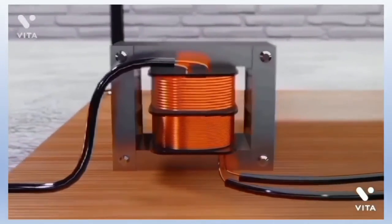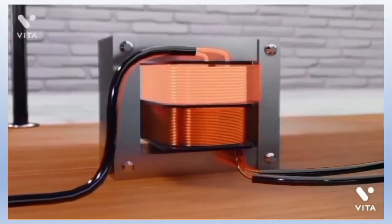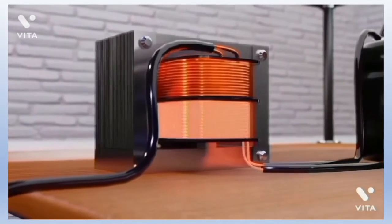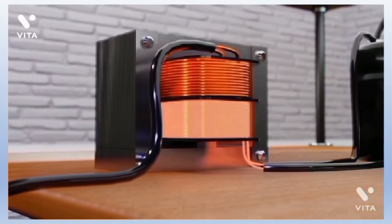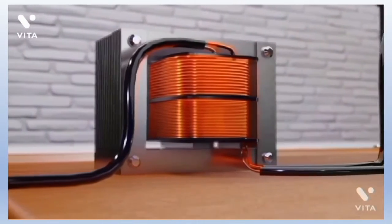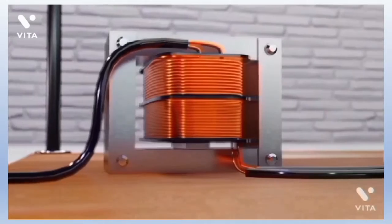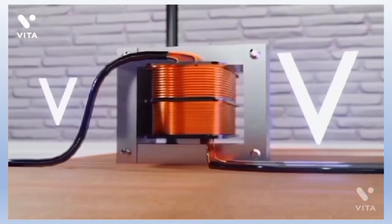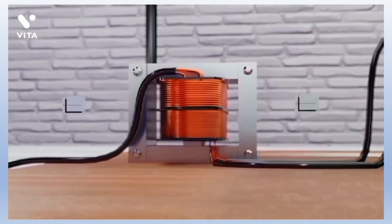A primary winding, which is connected to a current source and generates a magnetic flux, and a secondary winding, which converts again that magnetic flux into a current. But the interesting thing is that if the number of turns on the secondary winding is greater than the number of turns in the primary winding, an output voltage larger than the input is generated. Primary coil affects the secondary coil.